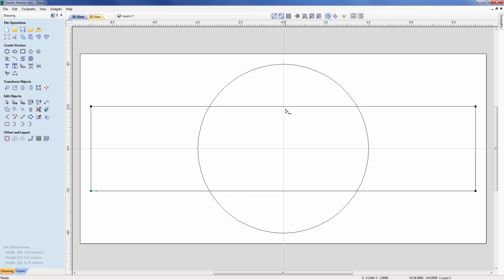Now what I need to do is to turn that into a physical point that I can then modify its parameters. So I'm simply going to hover over it, right mouse key, insert a point, then I'm going to go over it again, right mouse key, properties, and it's going to give me currently what that absolute position is, which is at x0, y2. Now I know that I need to move that down by 0.5 of an inch. So I'm just simply going to select that and say I want an absolute position of 1.5 and apply. Okay, so let's move that down by half an inch to y1.5.